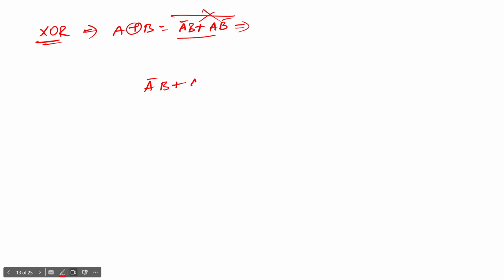So see another complementary circuit design. Okay, let's move to some logic, the XOR gate. So now we all know about the XOR gate operation. A XOR B, if you extend this, is A bar B plus A B bar. So you can't do it directly because there is no bar. If you do it directly, you get the complete bar, so it will be wrong. That's why you have to apply the double complement: A bar B plus A B bar, whole bar, whole bar. One is for output and another for the equation.